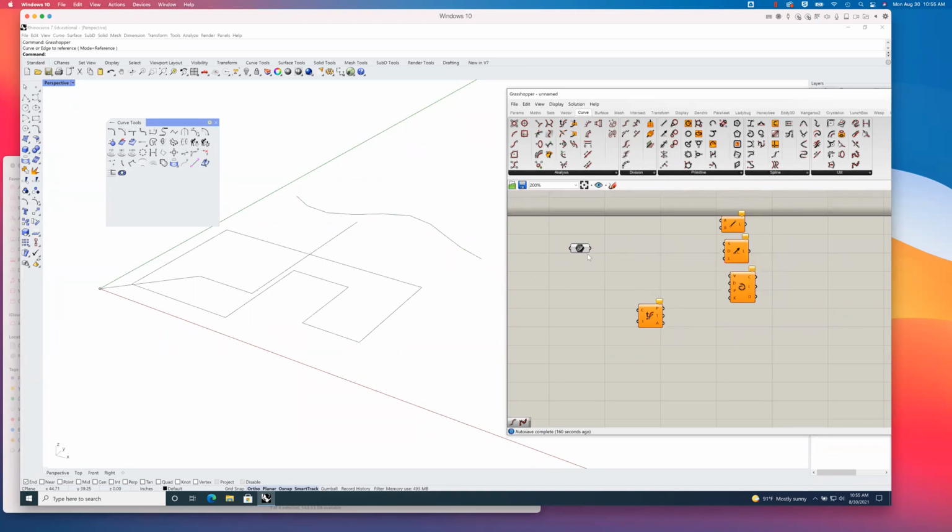We did that before. We can also take a curve, and again, I'm going to right click and say parameterize the curve. What that does is normalize the curve. So it takes the curve and says, okay, the start point of the curve is 0, the end point of the curve is 1, regardless of the length. You didn't know this, but Rhino actually remembers where you started clicking when you made a line or curve and where you stopped, and remembers the start and the end for you. And as a result, Grasshopper uses that.